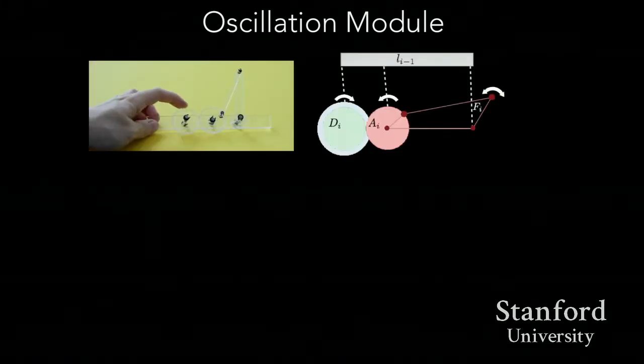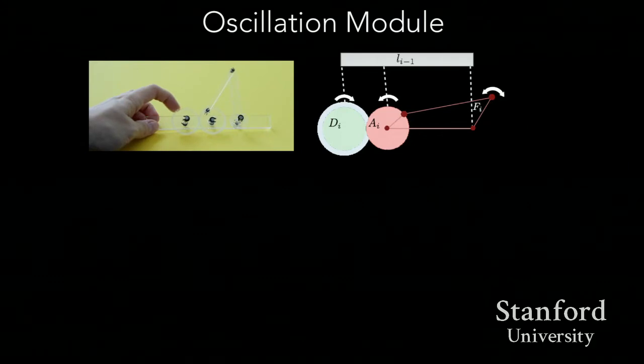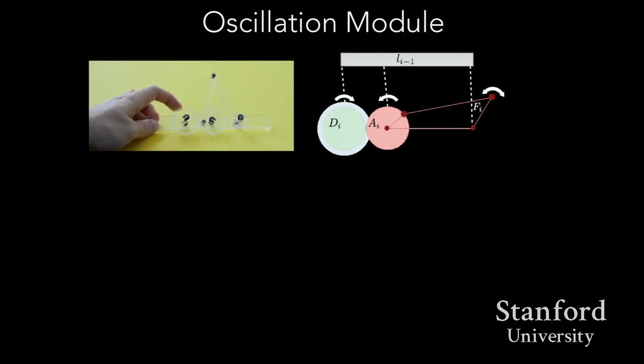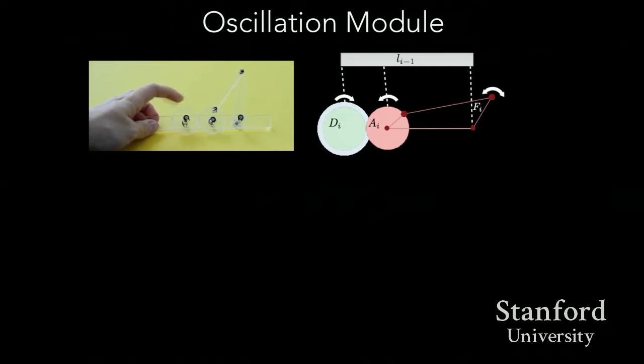The way we had of simplifying the problem was to come up with a single fixed, what we call oscillation module, that has this fixed design, has certain sets of gears, and in this case, a 4-bar linkage that's connected to the gears to turn rotational motion into oscillating motion. And then we attach these oscillation modules to each joint in the model. So now we have basically the same repeated design. It's just a modular design that's repeated across all the different joints, which really reduces the space of different solutions we have to search over.